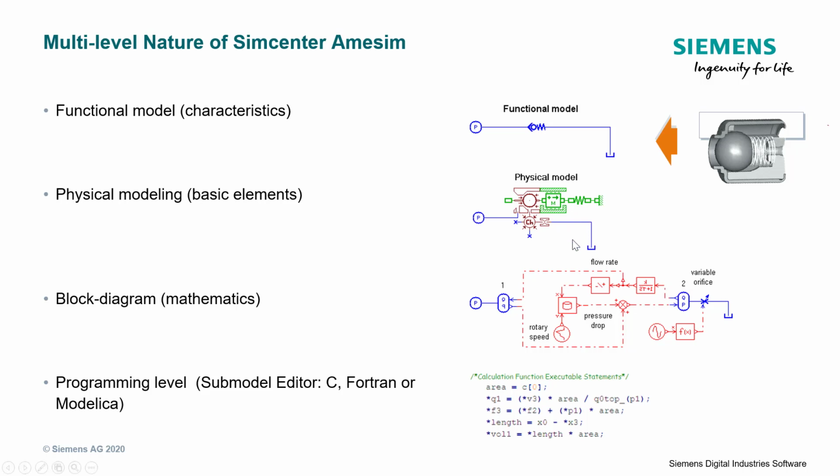These details can be modeled to model the physics of the check valve as well as using the so-called block diagram. One has the opportunity to use mathematical approach to the modeling. For example, using the signal and control library, the user can create equations that represent the flow rate and the pressure drop of the particular valve and model that valve with those kinds of components.